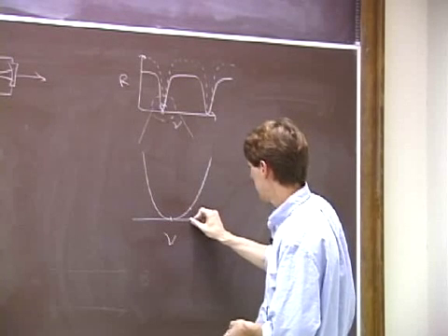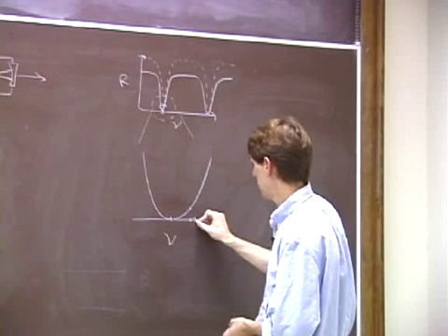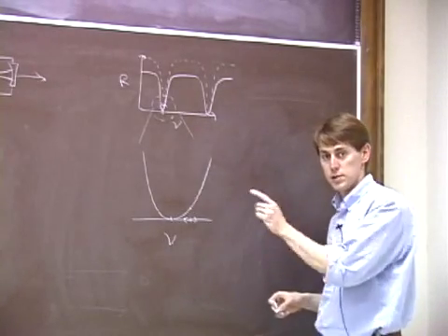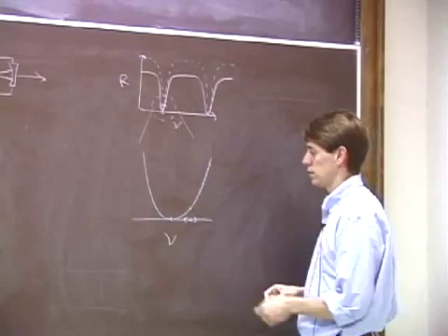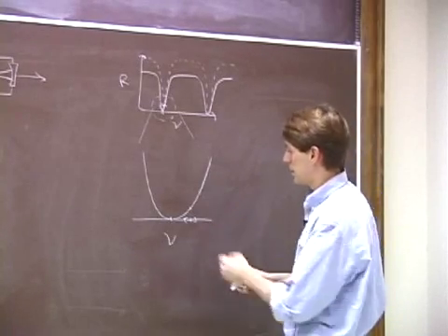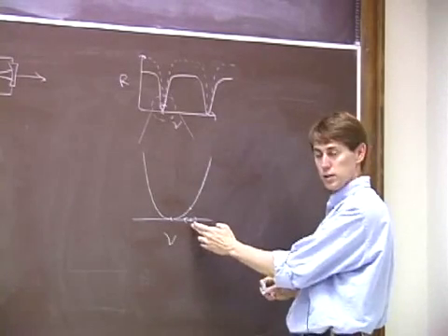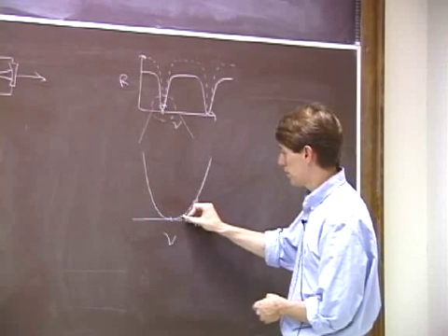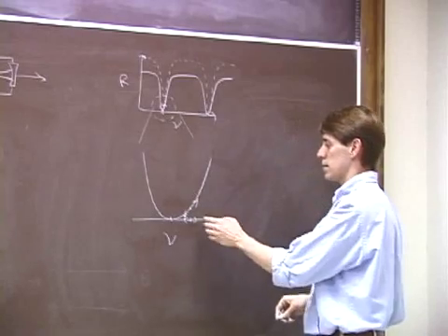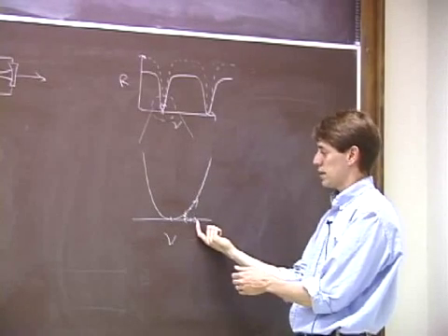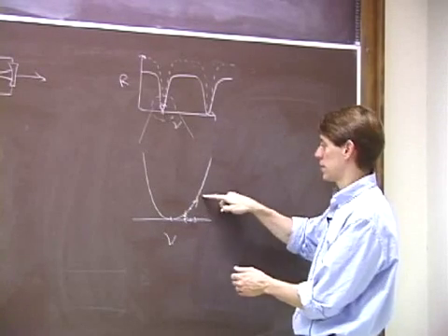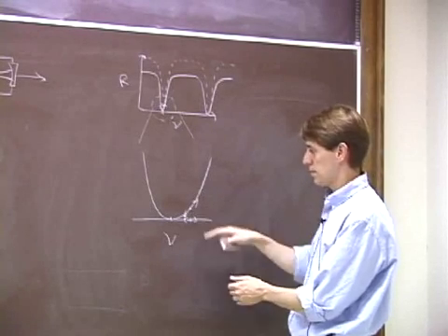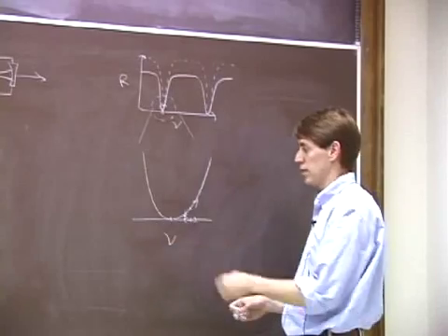And let's say the frequency at which we operate gets modulated, dithered back and forth sinusoidally at a nice regular signal. Then if the frequency moves up, what goes into the photodiode does this. As the frequency gets increased, the reflected power increases. As the frequency decreases, the reflected power decreases. On the other side, it's the other way around.